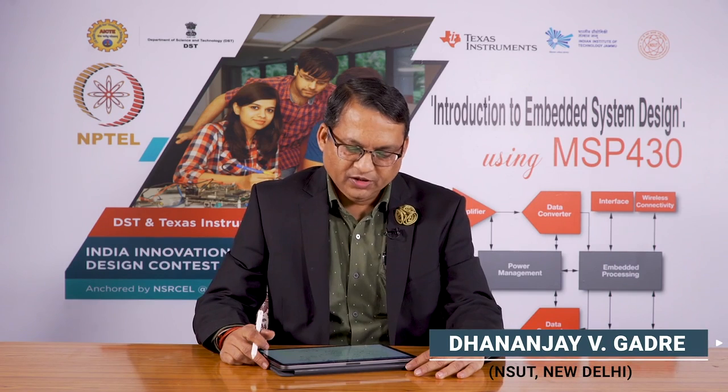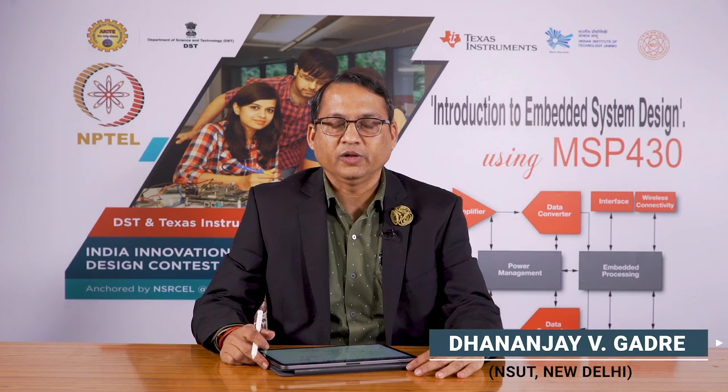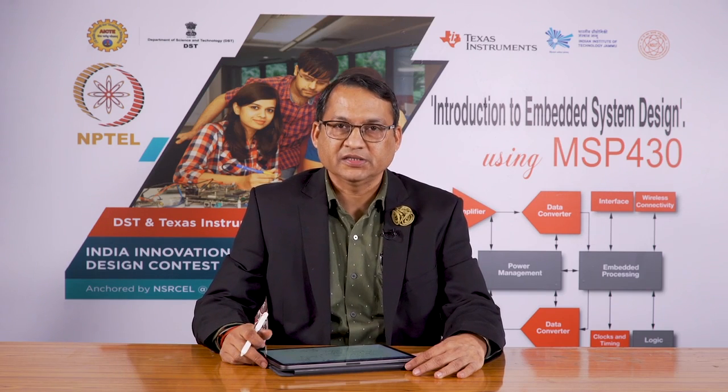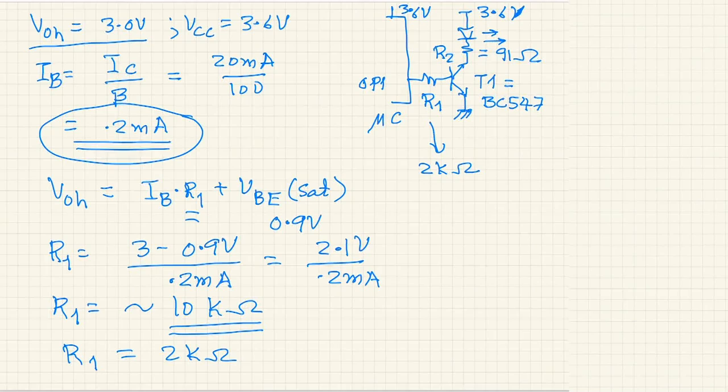In the last session we looked at various ways of controlling the LEDs through what we call low side switching. In that we looked at various options to increase the current through the LED, and we came up with this configuration of driving a LED with the help of an NPN transistor operated in a switch mode. To operate the transistor in the switch mode, it has two options: either the transistor is saturated or the transistor is cut off. When the transistor is cut off, there is no current through the collector. Therefore, in our case the LED will be turned off.